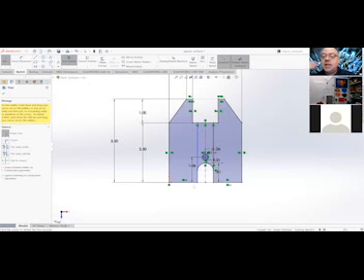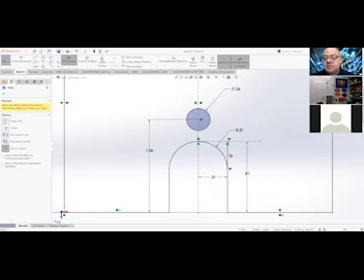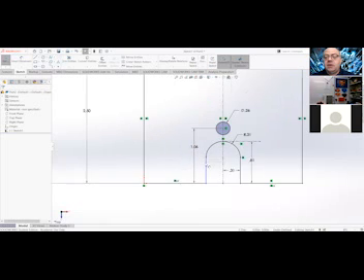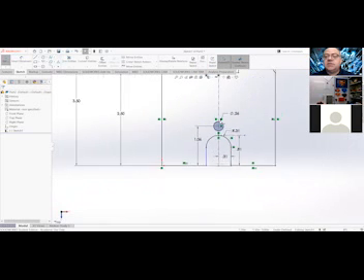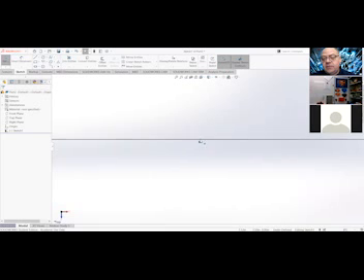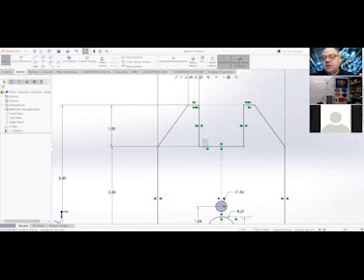So there are two. And then trimming these entities down, I just go to Power Trim. I select, trim, select, trim. Now I've got to come in and take this piece off. Notice the gray goes away if there's a non-connected endpoint. We do that, and the gray's still gone. I'm all worried now. Not really. The reason the gray's not back is I left an extra endpoint up here. When I trimmed this line, I got really close, went just above, and left an endpoint. So I'm just going to go ahead and select and delete that one out if I can.